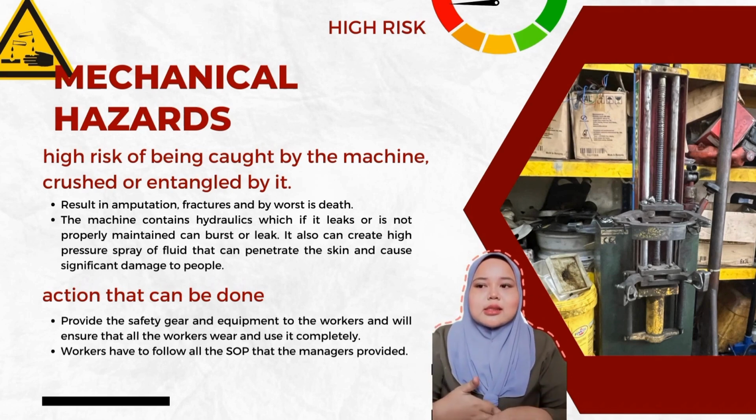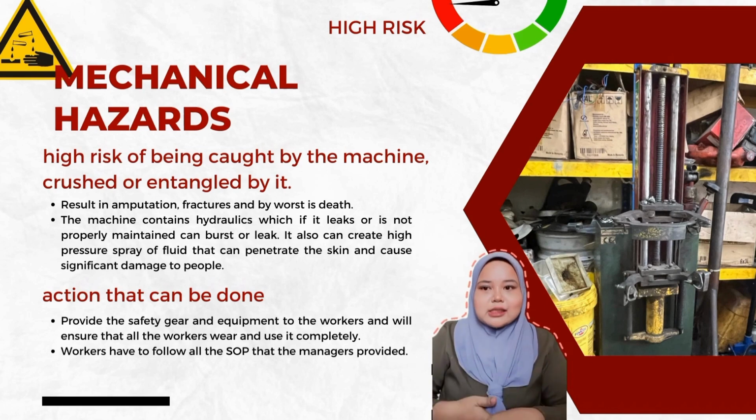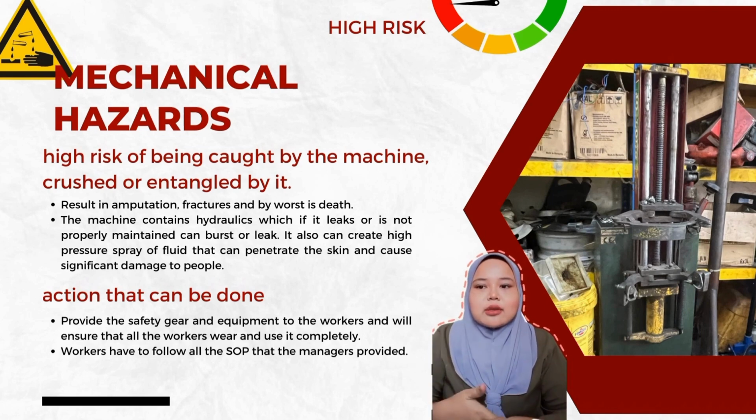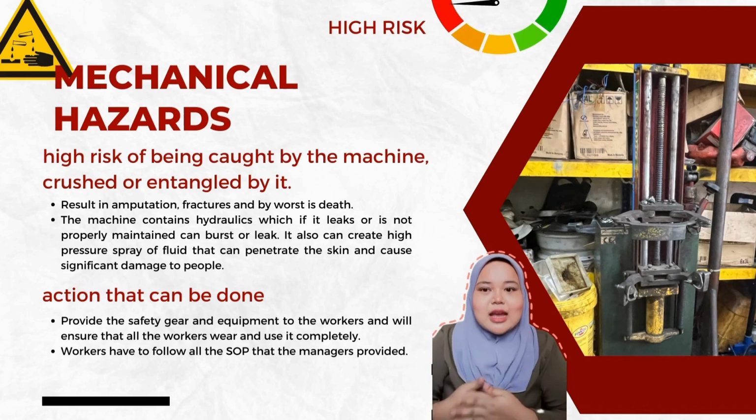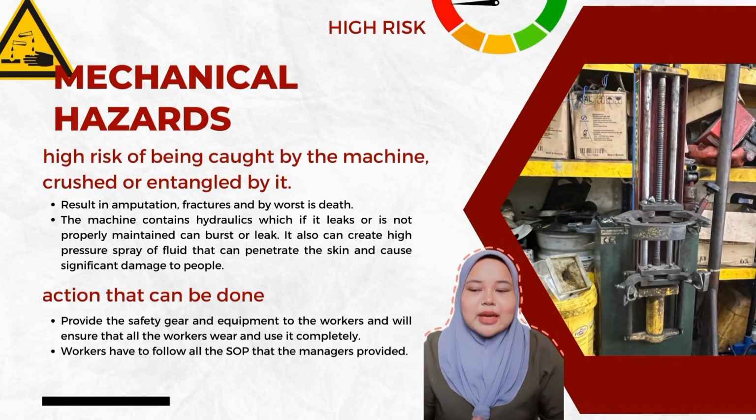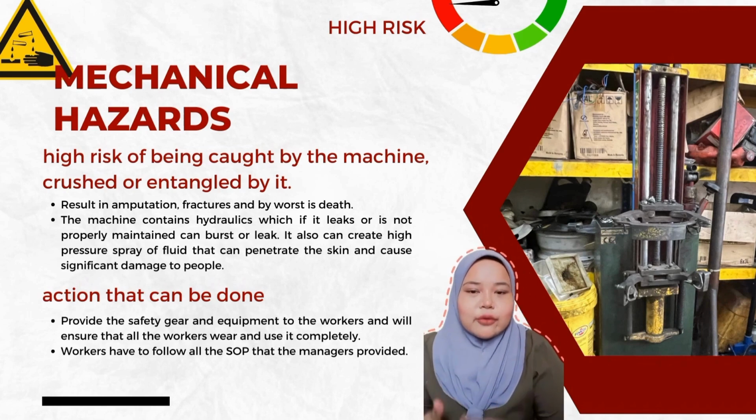And the result is amputations, fractures, and worse, the machine contains hydraulics, which if it leaks or is not properly maintained, can burst or leak. It can also create a high pressure spray of fluid that can penetrate the skin and cause significant damage to people. So the action that can be done by the manager or the owner of the repair shop